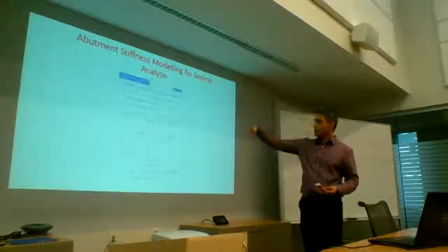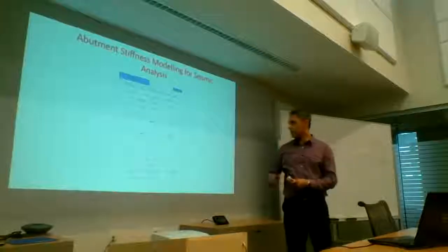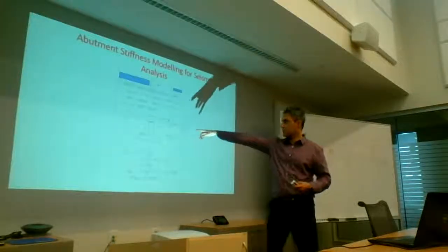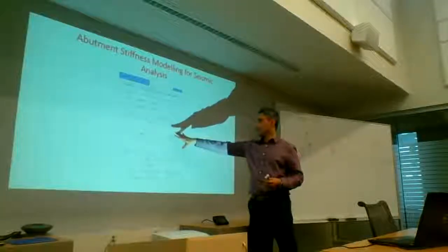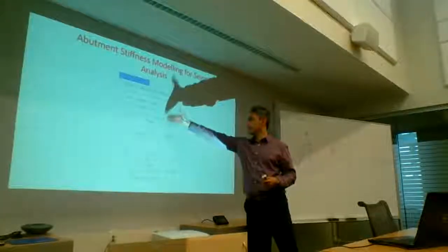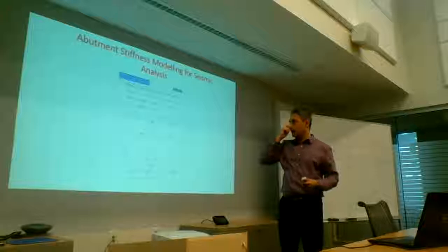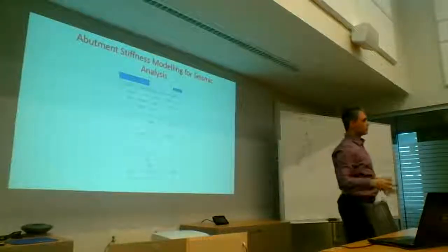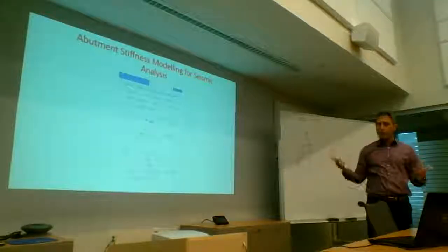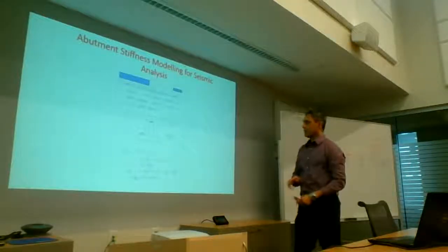So this is just showing you a quick calculation for the abutment. This is what I was showing you earlier. This is a semi-integral abutment, basically, so you don't need to put a joint here anywhere. These bridges are relatively maintenance-free because you don't have any joints. The water doesn't seep through. They give you a lot of benefit.